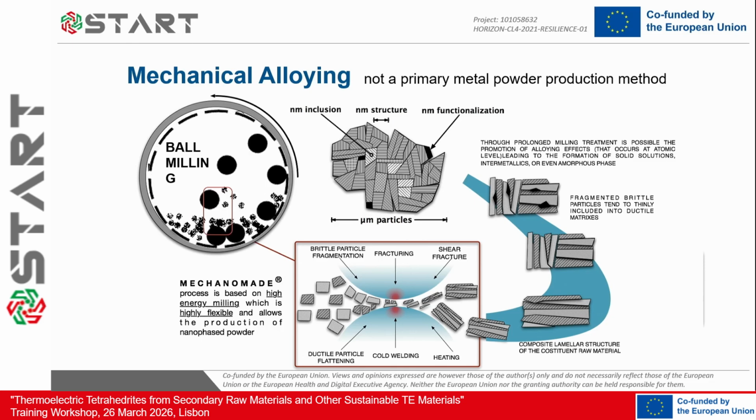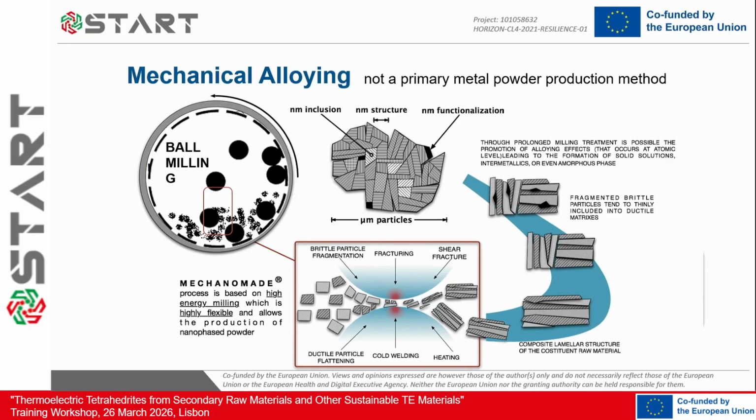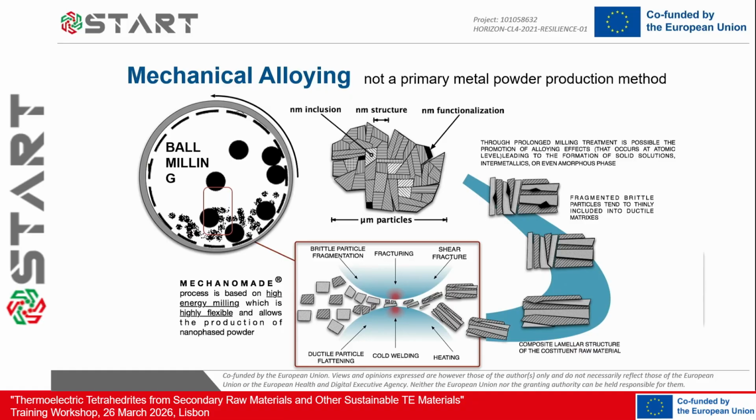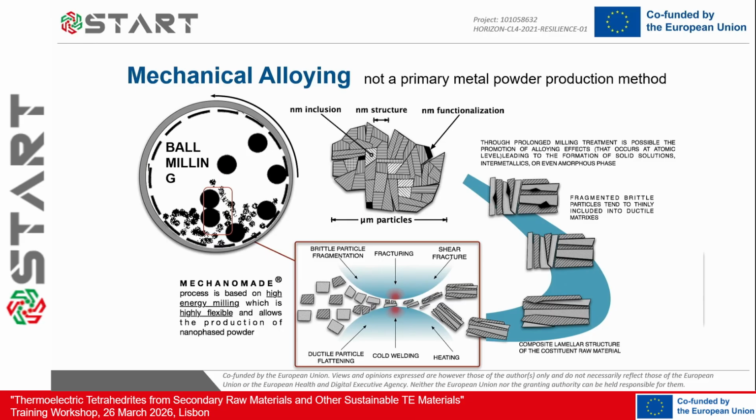What is it exactly? In ball milling, the mixing is happening in the solid state. We are putting together at different phases all the material that we started with. There are effects of flattening, welding, cold welding, and all of this, after a certain amount of time, brings you to the formation of new phases, the dispersion of oxides or hard phases that you have in the material, and eventually the formation of what you might expect to get from the ball milling, which is the final phase.